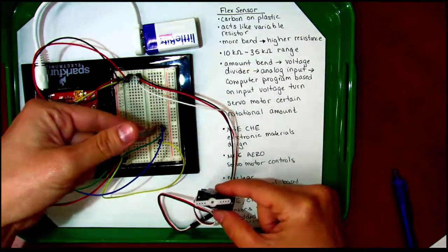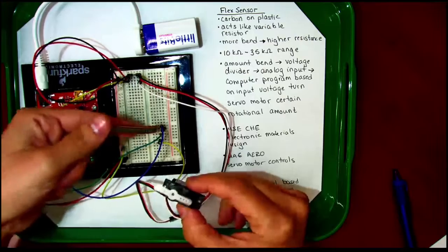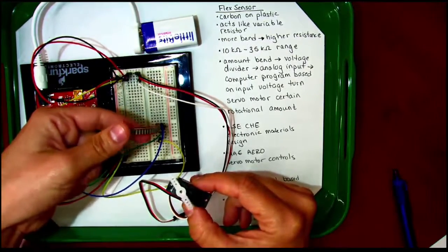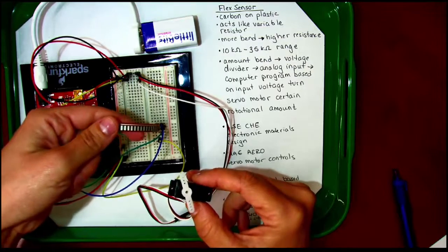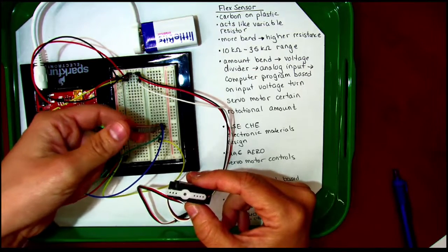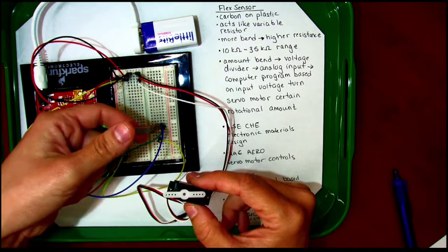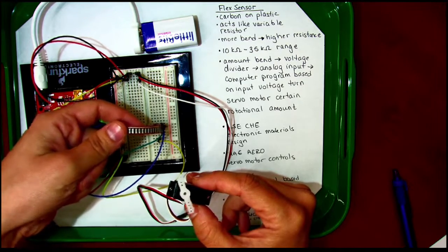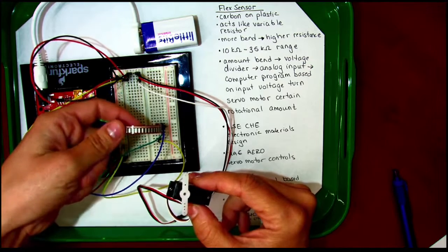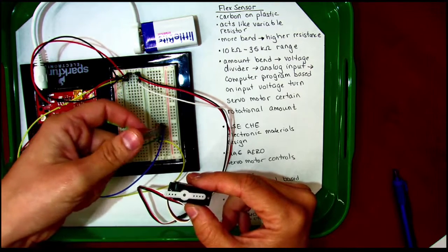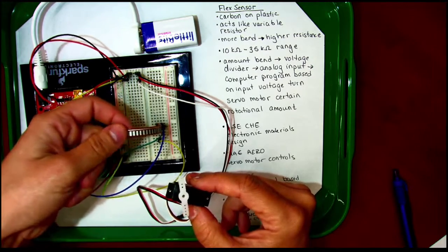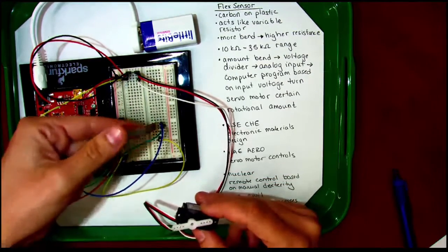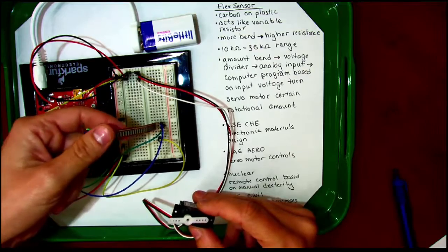So I'm going to put one finger underneath and my thumb on top. And you see as I bend it, I'm varying the resistance, which varies the voltage that the little computer program then says to the servo, if you receive this much voltage, rotate this many degrees. If it goes back down to so much, rotate back. So it's a simple device, but these are some of the basic circuit concepts: a voltage divider, different types of variable resistors are actually sensors you might buy within your majors.